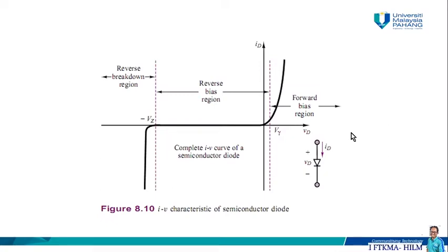Next we also have a phenomenon called the Zener breakdown. This is related to the avalanche breakdown. It is usually achieved by means of heavily doped regions in the neighborhood of the metal semiconductor junction. The high density of charge carriers provides the means for a substantial reverse breakdown current to be sustained at a nearly constant reverse bias. So we are going to have the Zener voltage, called Vz.